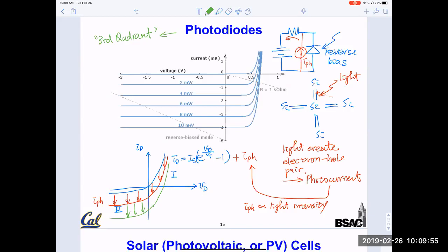So this example here kind of zooms out to higher current, higher voltage. You see a more flat IV curve here. And with the current, you can see clearly 2 milliwatt, it drops down to nearly, not quite 1 milliamp. And 4 milliwatt is almost equal spacing. So this just goes equally here. And the sensor circuit basically tries to pick up this current, amplify this current. And eventually you combine all your two-dimensional pixels, you get the picture.